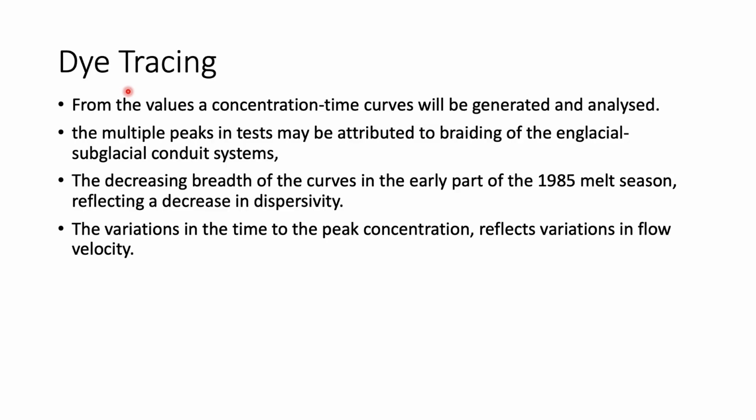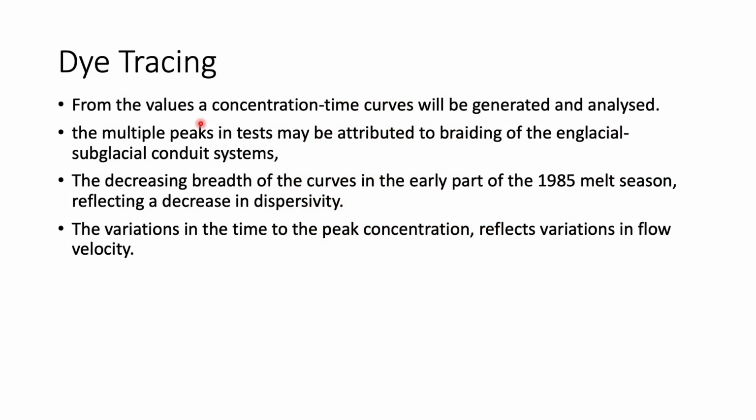So how do we continue the dye tracing studies? From the values, a concentration-time curve will be generated and analyzed, because we have dropped dye at one particular area, that is the moulin area, and samples are collected at a very far off place. Once water is collected at different times, people use a concentration-time curve to analyze how much time it takes for the dye to reach the sample site. The multiple peaks in the test may be attributed to braiding of the englacial and subglacial conduit systems.